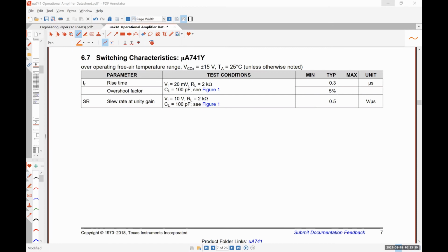If we were to further increase our frequency, we get triangle waves. This means it's having such a hard time catching up with the changes that it's no longer even giving us anything remotely sinusoidal looking, okay? So while this can look similar to gain bandwidth product limitations because the amplitude is decreasing, it's a slew rate problem because we're no longer seeing the sinusoidal output that we're expecting. Our amplifier literally cannot catch up.